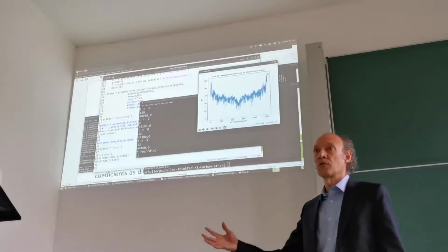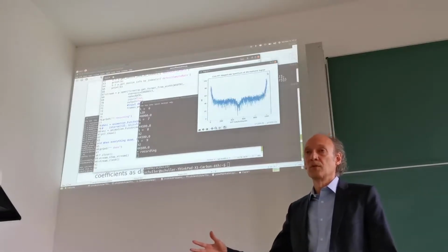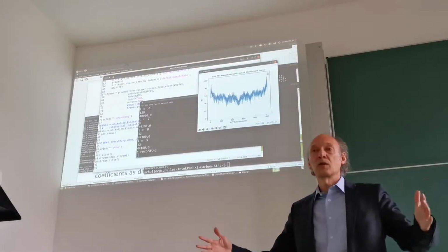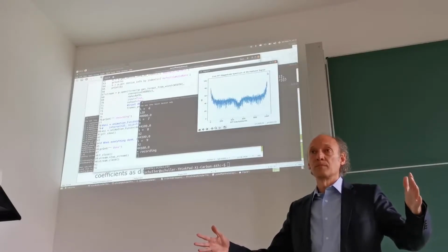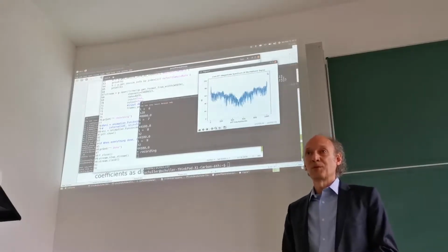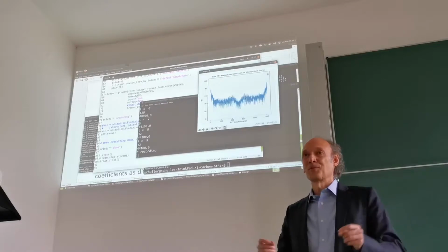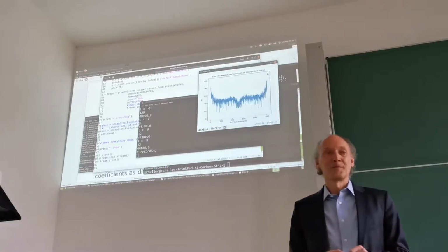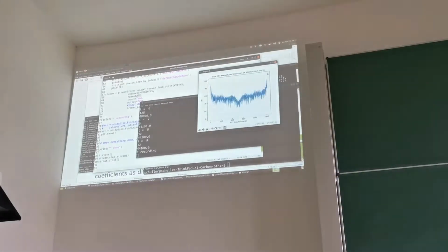We are not computing k equals 1024 because that's identical to k equals 0. We cannot distinguish it from k equals 0. Here, to the left side, we have the low frequencies, starting from 0 and then going up. And the same on the right-hand side. Low frequencies going down means higher frequencies.